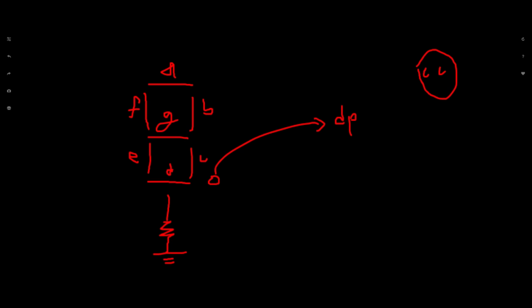So I'll just connect B with the positive of Arduino. There are two ways: either you can connect it to the positive or you can connect it to the digital pin and then write the code. So 1 is displayed just by activating B and C. I displayed number 1 on the 7 segment display.